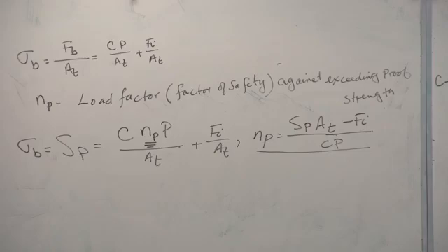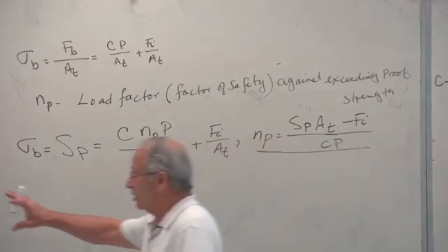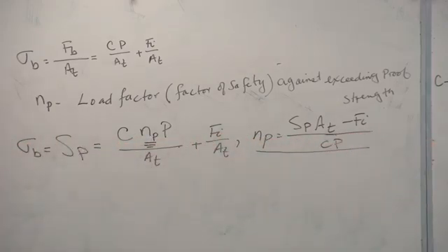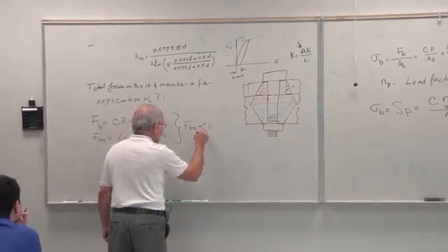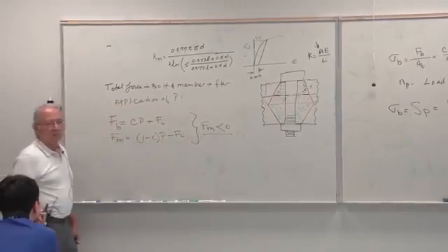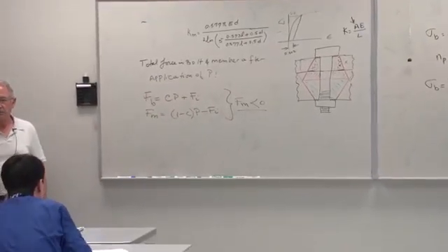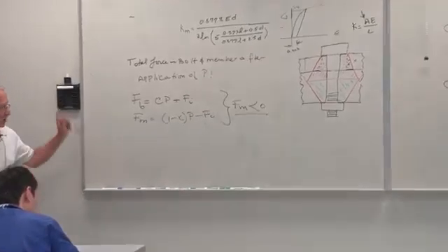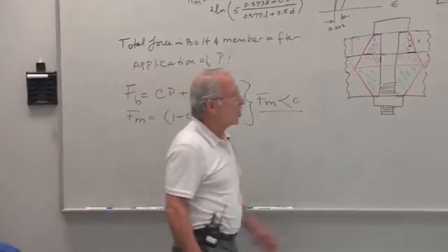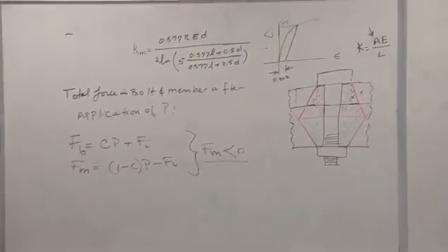That was one consideration. And remember, both of these equations are good. Both of these are good if there's compression in the member. The load in the member must be negative, or else these are no good. All of the load goes into the bolt in that case.